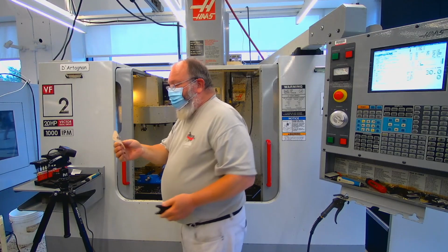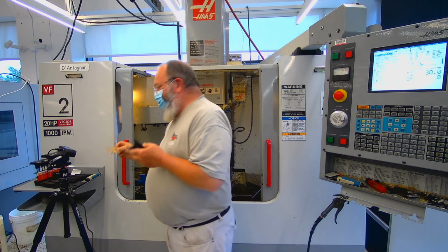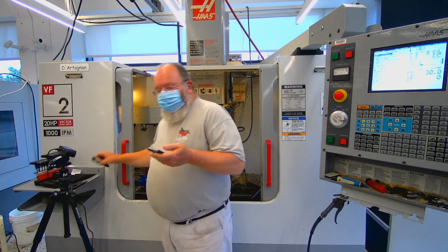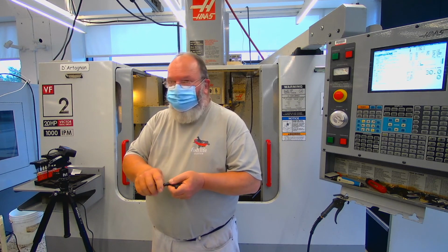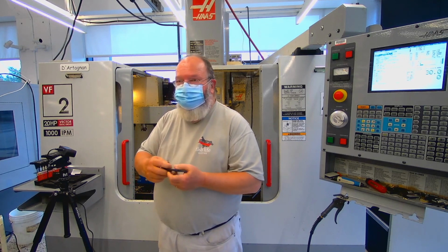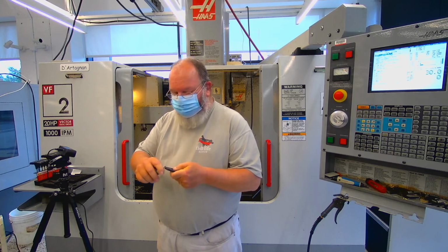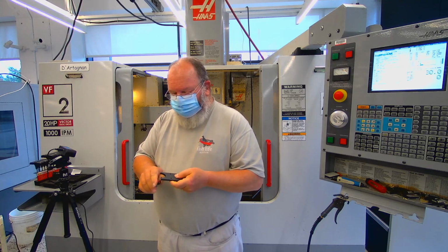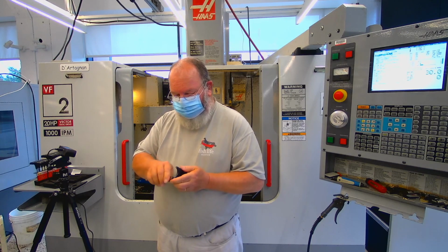I can't pass this around because of the space age material called double-sided sticky tape. That was our work holding device for today. Now, anytime we cut materials with any kind of cutting tools, we're going to wind up with razor sharp edges that we have to deal with. This process is called deburring. This is a very basic tool called the swivel deburring tool.